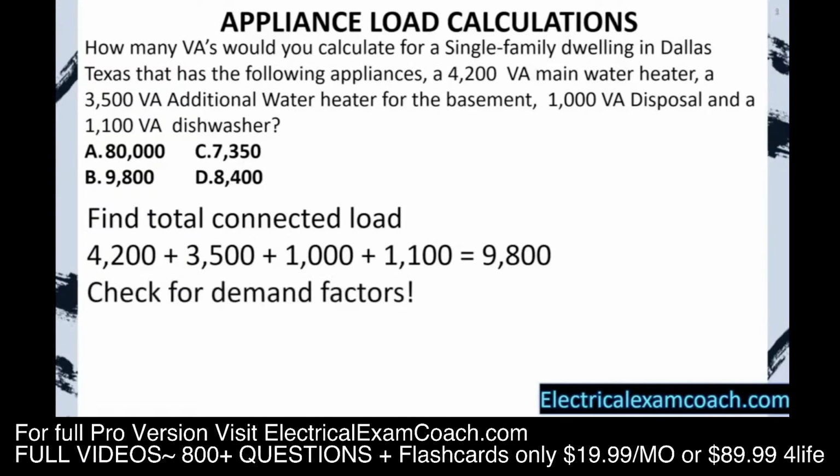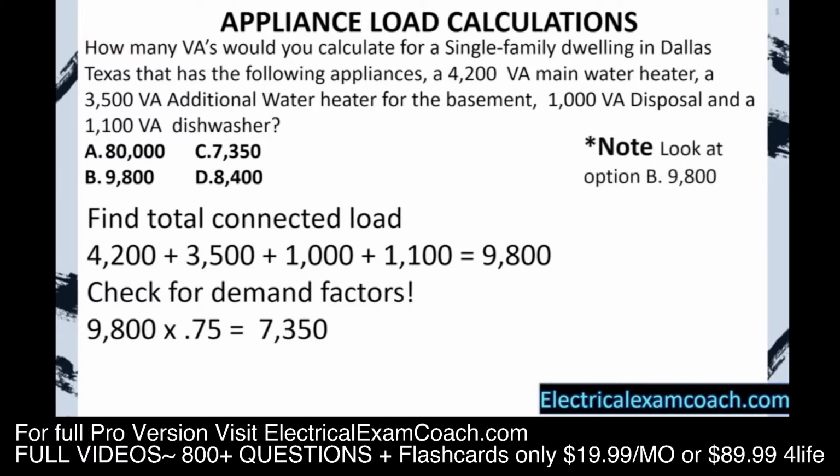Now, we check for demand factors. Sure enough, we have 4 or more fixed appliances, so we can apply the 75% rule. We take 9,800 multiplied by 0.75. That gives us a new reduced load of 7,350 VAs. I want to note that if you look at option B, it was 9,800, as if you didn't apply the 75% rule. You got to be careful.